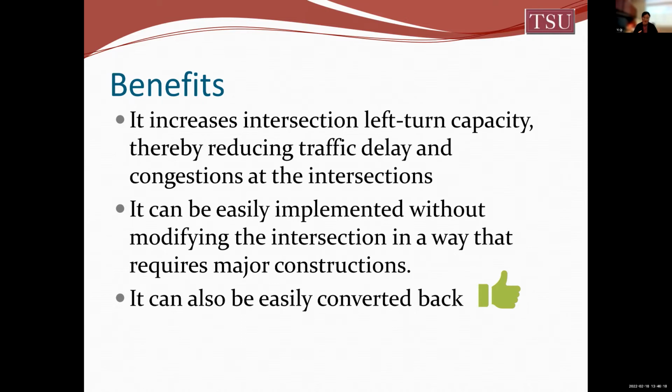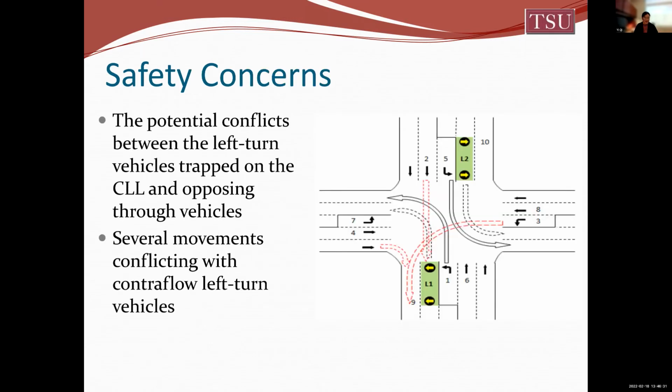If we use the control flow left-turn design, it's very easy to take it back. You just take off the pre-signal lights and erase the pavement marks. You can easily take it down. So this is the benefit of using this new design.